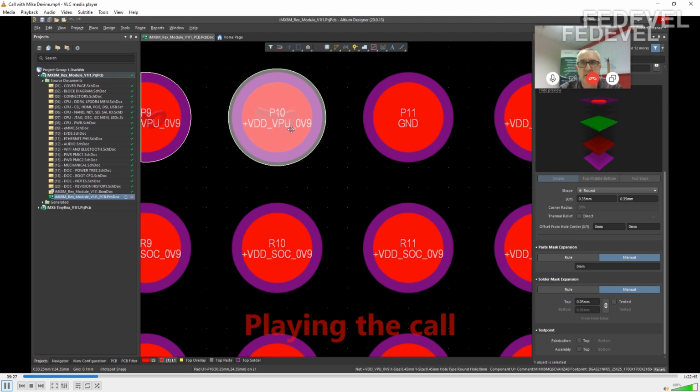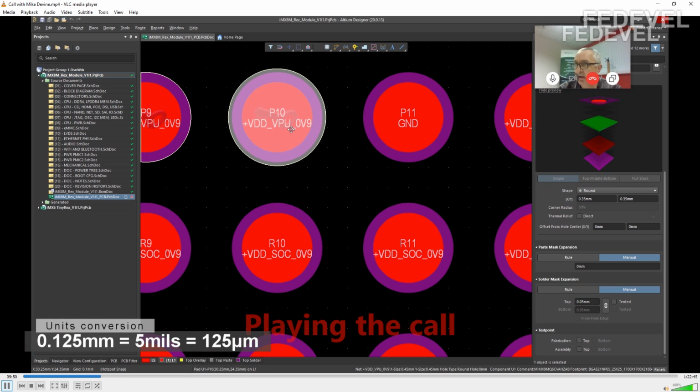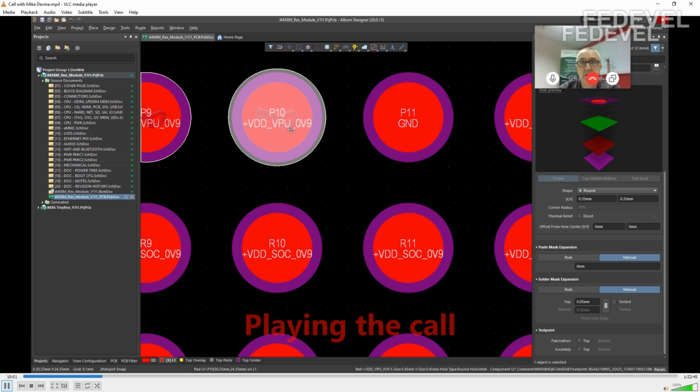Minimum size of the pad. Ideally, we were looking for 50 micron annular ring. So if it had 125, and then 225, so you could have a minimum 225 micron BGA pad. And how deep you can drill if you use 125 drilling? You can have 100 micron dielectric. So the next layer basically can't be further than, or the pre-preg thickness can be like 100 micrometers.